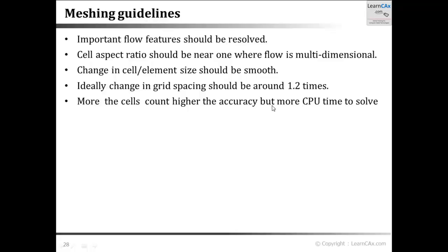But it is not always possible to generate mesh within a large CFD or CAD model, because it will give a huge mesh count, or a huge number of cells, which will not be possible to solve using a smaller CPU, or it will consume a lot of memory or a large amount of CPU runtime. So the more the mesh count, the longer the project takes. In order to reduce the CFD simulation project time, we have to use a sensible or optimized meshing strategy.